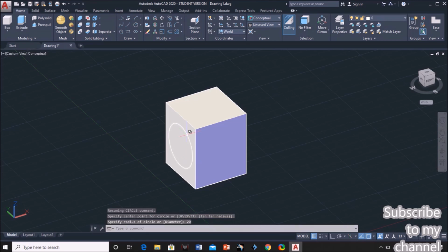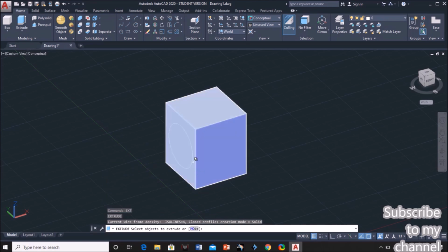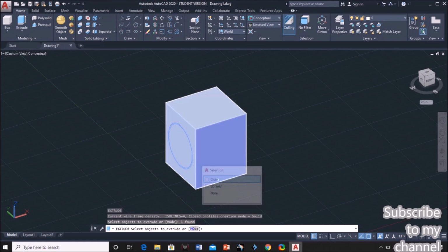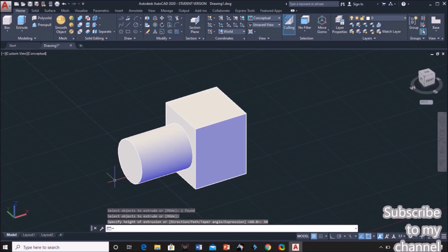Now I need to extrude this circle in this direction. For that, give the command as extrude, EXT enter, select object, that object is the circle. So click on the circle. Next, click on enter. Now give the specified direction, that is the height of the extrusion. I am giving it as 50, enter. So like this we have drawn the circle in this direction. Now on this face I need to remove the circle.